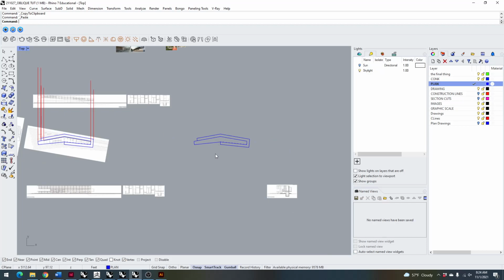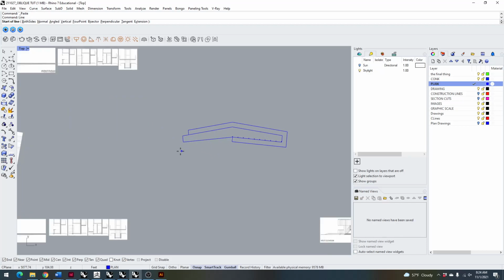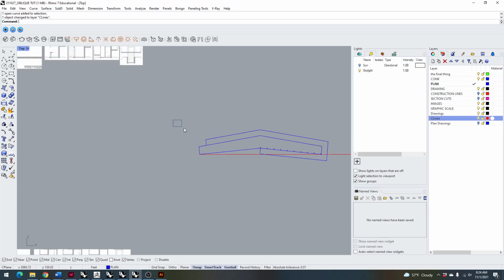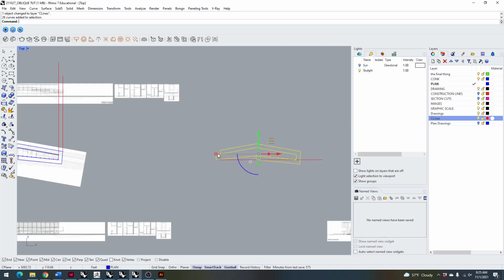Although the next step of drawing a plan oblique drawing is that we'll rotate our plan by some angle. Erica and I have elected to rotate it by 45 degrees for the purpose of this tutorial, but you can also rotate it 15 degrees, 30 degrees, or 90 degrees in certain cases, and still make a plan oblique.